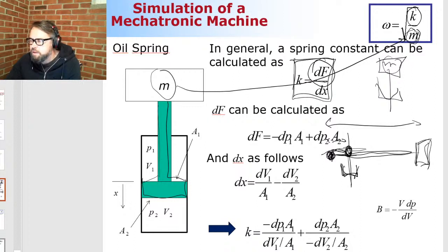This here is a change of the force. How can the force that is produced by this hydraulic cylinder be changed? Force will be computed as pressure multiplied by the corresponding cross-section area. So it's a pressure P2 applying on this diameter of the cylinder piston.